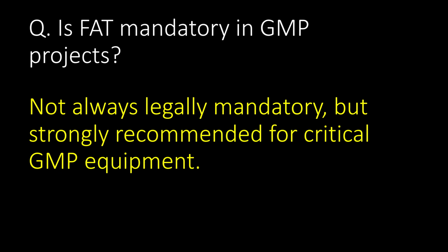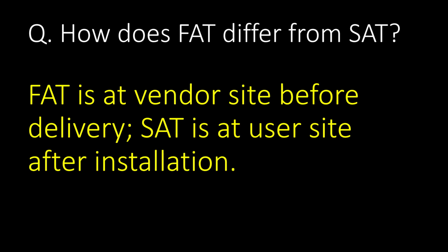Is FAT mandatory in GMP projects? Not always legally mandatory, but strongly recommended for critical GMP equipments. Very frequently asked question: how does FAT differ from SAT? FAT, that is factory acceptance test, is at vendor side before delivery, whereas SAT, that is site acceptance test, is at user side after installation.